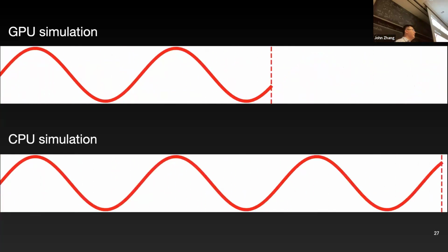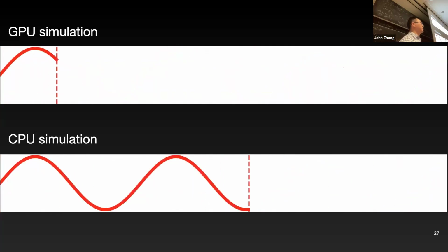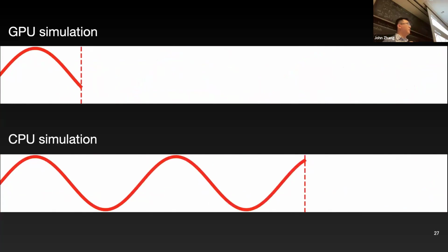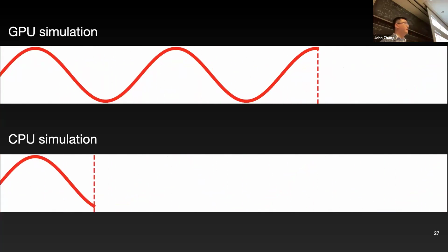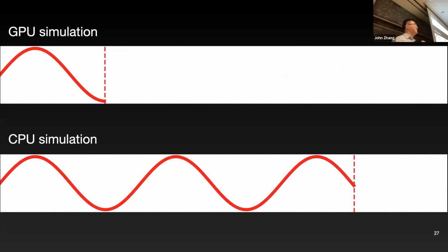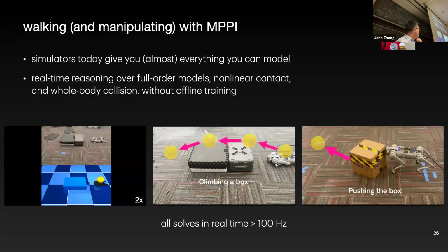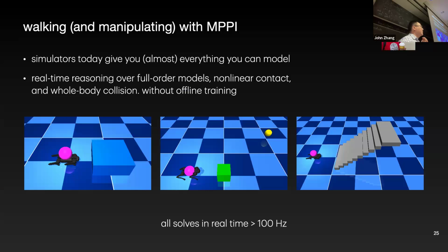And I would argue that for real-time control, you want to close this real-time feedback loop, as opposed to getting as many samples as possible and finding a better local minimum. Philosophically speaking, when you're doing real-time optimal control, the longer you spend optimizing a problem from a given previous state, the more your robot drifts from the problem you're solving.